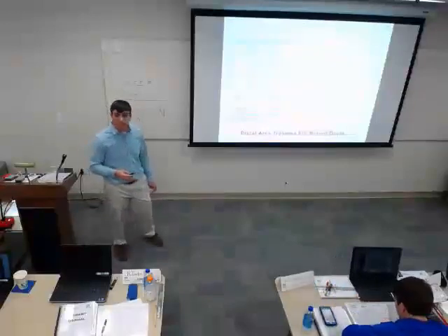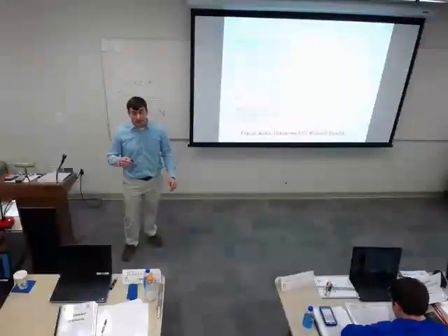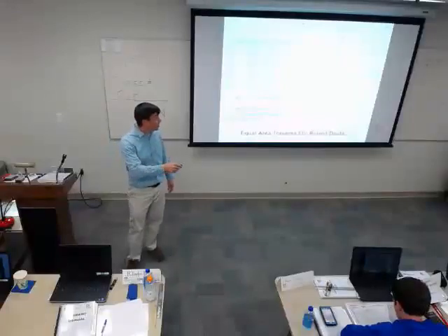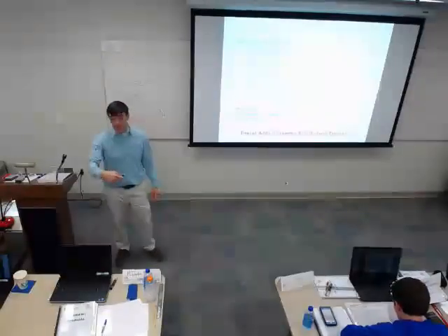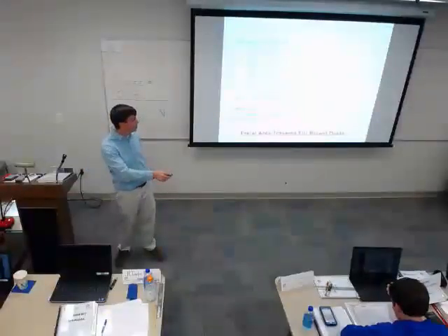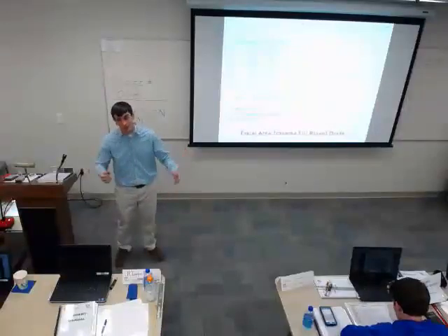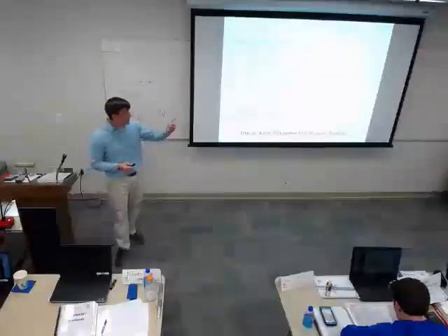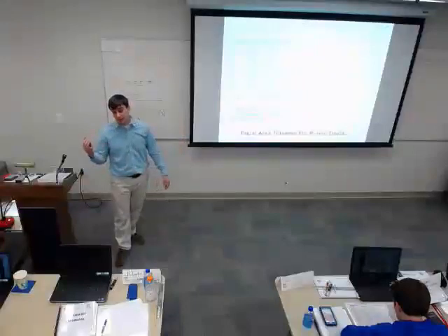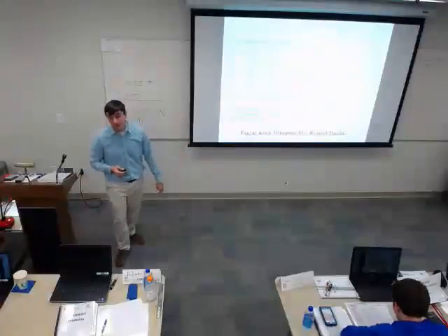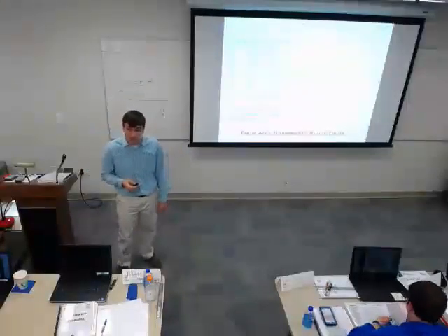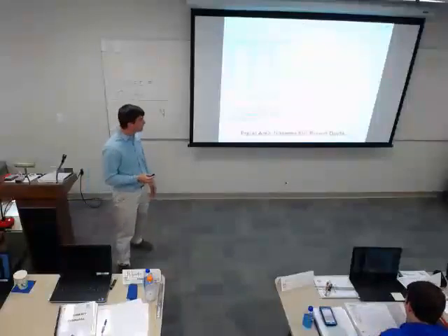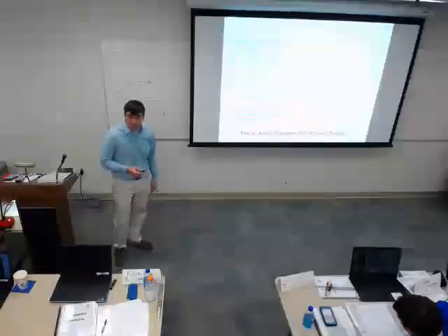Why don't you measure the center? I guess it has to do with the velocity being much higher in the center. However they came up with this equal area average, they chose to leave it out. I don't know. But that same process is in all the TAB standards as far as how you take that. You don't get one in the center of a round duct. Whoever did the math originally came up with that.